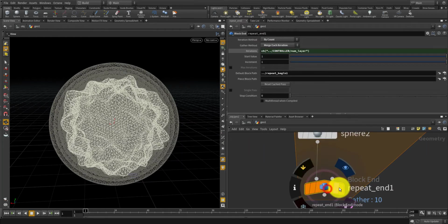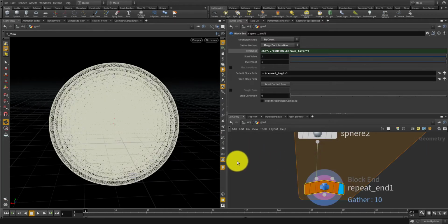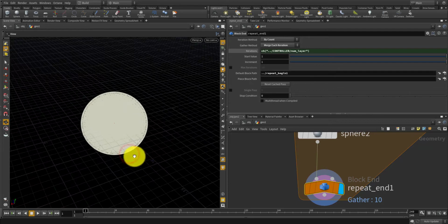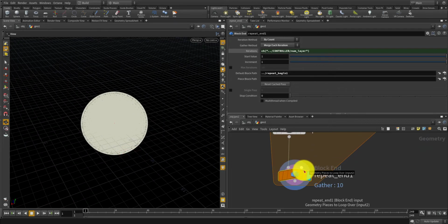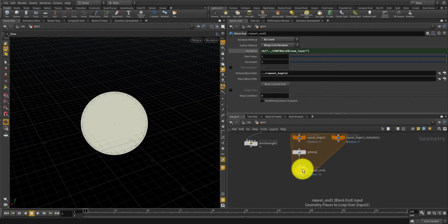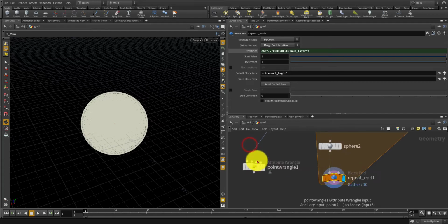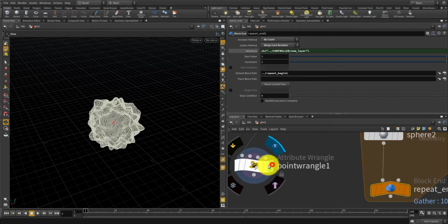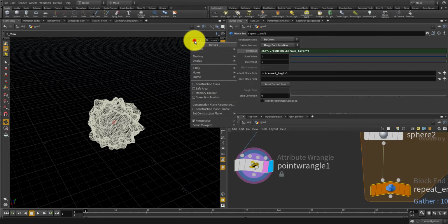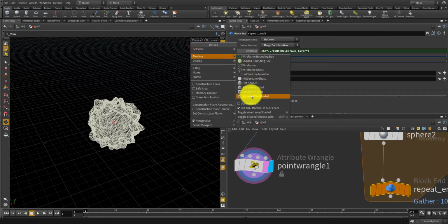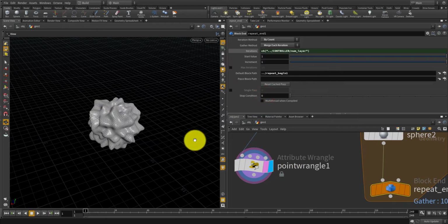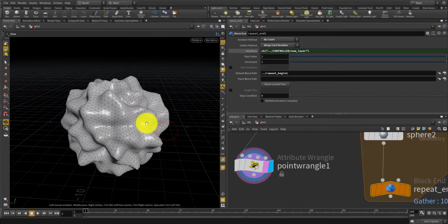Now I have all these spheres laid out, and so I want to use these spheres plus the base surface, the base mesh, to make an intersection to get a contour curve.